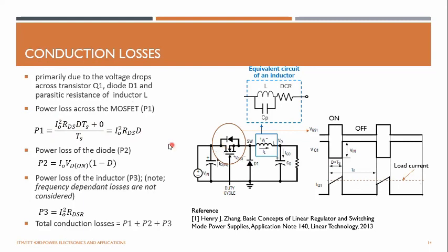So if you want to get an efficient system, you have to always find a suitable power MOSFET which has the lowest RDS on resistance. Typical values you can find are 10 milliohms to 60 milliohms or 100 milliohms. So it is always better to go with the lowest possible RDS on resistance. And I squared is the square of the load current, which you can't control in the design. And based on the duty ratio also, your power loss increases.